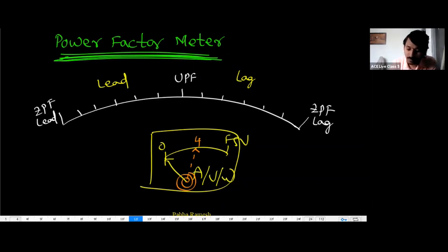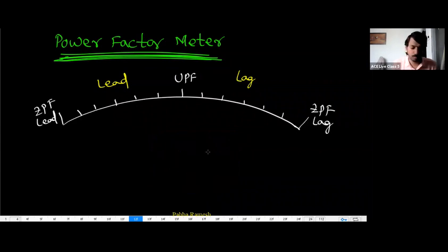But concentrate here. In this entire power factor meter, suppose I have connected some load and some supply is given. Assume it is showing some 0.6 lagging, or 0.4 lagging. Well and good. After switching off the supply, the pointer has to go back to which value? That is my question. People are saying it has to go back to the initial value. Come on, guys. In this, nothing is the initial value. I already told you, nothing is the initial value.